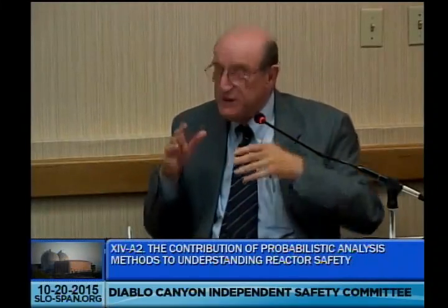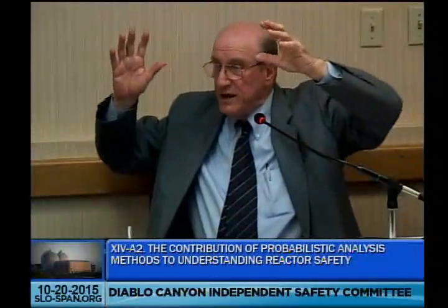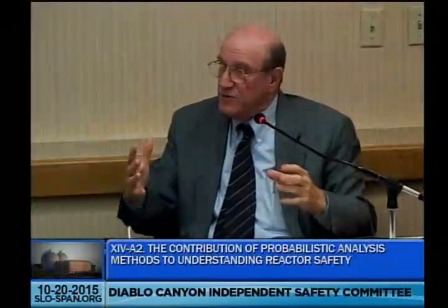Now I just have to, before I put up the slide, explain. The way this was done was all this stuff was designed using all the industry codes that have been in existence, although the nuclear ones have more rigor and certain more margin. And then the AEC and the industry together put together, originally it was a few, but now they have about 15 of these design basis accidents, like the one I said where you can't scram the reactor, it still has to be okay, or the large break LOCA, and then you still have to be able to cool the core. And you have to show that that's so, okay?